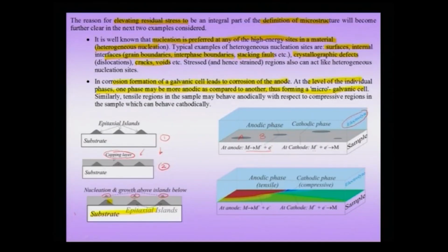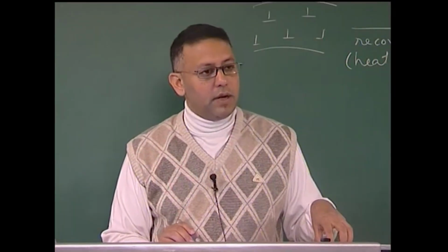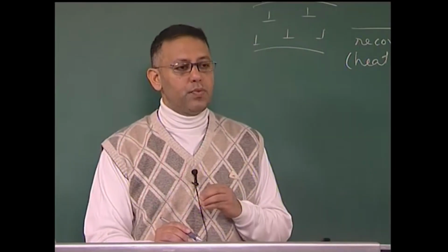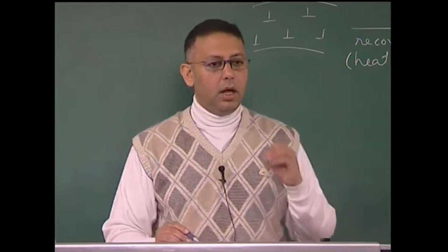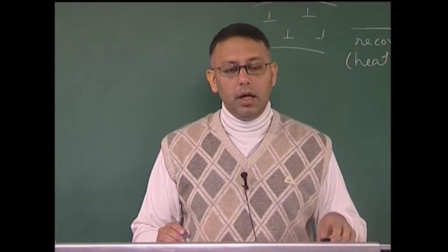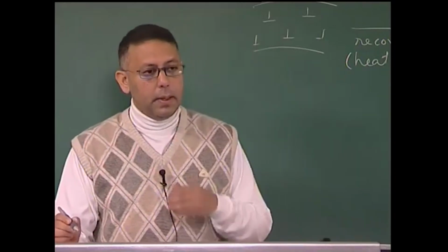This electron of course will combine with the metal in the electrolyte and deposit at the cathode. So, this will be the cathodic reaction, while the anodic reaction is that of dissolution. So, where is this electrochemical or galvanic cell forming? This galvanic cell is forming at the microstructural level. It is forming between two phases in the microstructure, phase A and phase B, and of course, in the presence of an electrolyte.